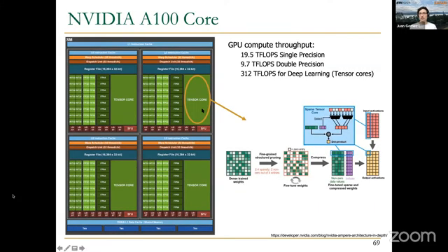But if you look at the internals of an NVIDIA GPU, for example, the GPU core, you'll see that they have part of array and part of SIMD, part of array and part of vector processor. Why is that? Because we have many different units. You see specialized for int32, floating point 32, load and store, 64-bit floating point, or even these tensor cores. But we also have several of these units. So we can operate both in time and in space using individual instructions or a single instruction string.